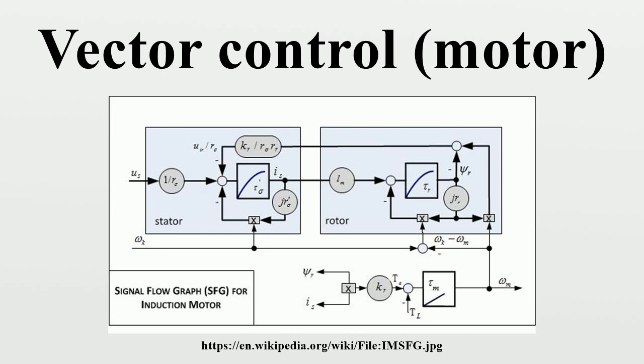In DFOC, flux magnitude and angle feedback signals are directly calculated using so-called voltage or current models. In IFOC, flux space angle feed-forward and flux magnitude signals first measure stator currents and rotor speed, for then deriving the flux space angle proper by summing the rotor angle corresponding to the rotor speed and the calculated reference value of slip angle corresponding to the slip frequency.